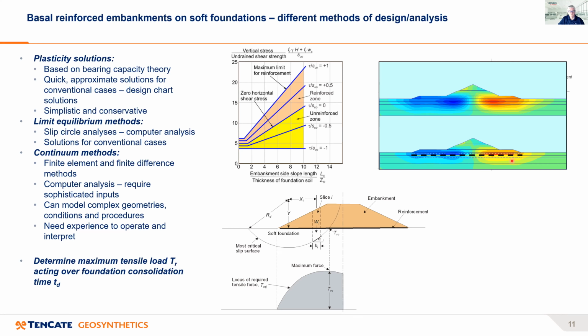Also, with these methods you can model quite complex geometries, conditions, and procedures. But again, I'll stress you need the experience to operate these and interpret them. So you have a choice of all three. And at the end of the day, what you're trying to work out is what is the maximum load in the reinforcement, and how long does this load have to last for?